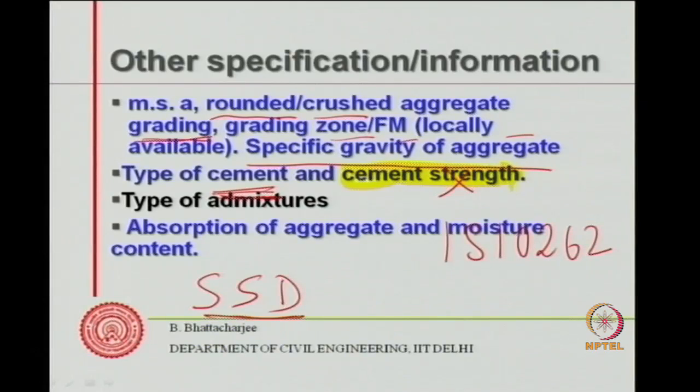What is the moisture content, how much is the moisture content related to SSD condition. That information is important, because in actual site moisture content may be different, so you have to do some adjustment accordingly.